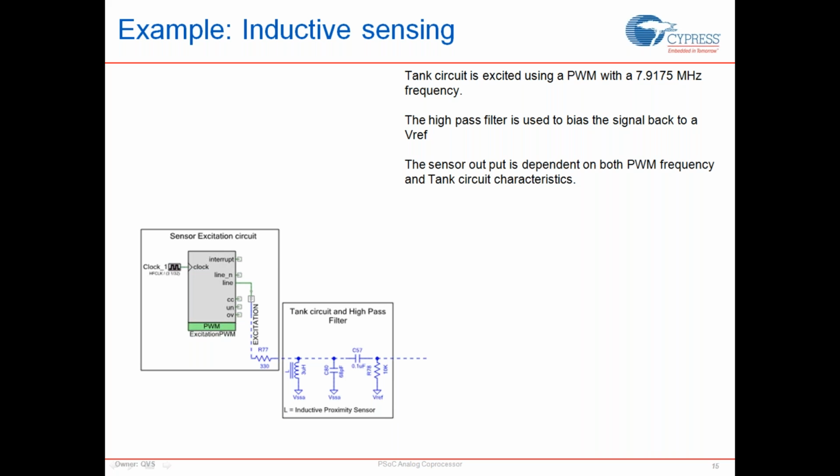And the reason I'm doing that is because I want to make sure that the frequency that I'm using to excite the circuit is somewhere on the slope and not at the peak. The reason is you want to have a linear response at the output when I move the resonant frequency around that. If I'm at the peak, the slightest variations would not cause a huge amount of variation on the amplitude. So keeping it on one of the slopes is more useful so that you can get a more linear response to your circuit.